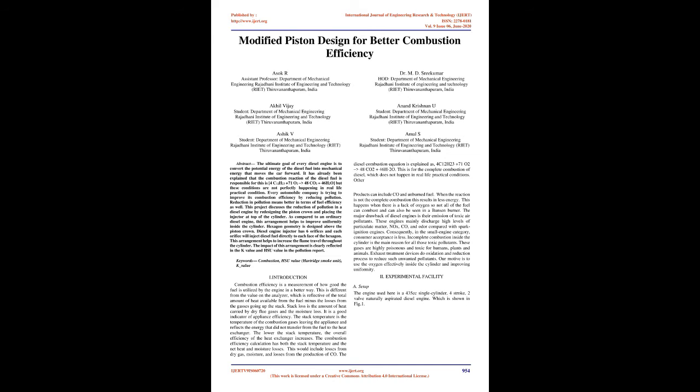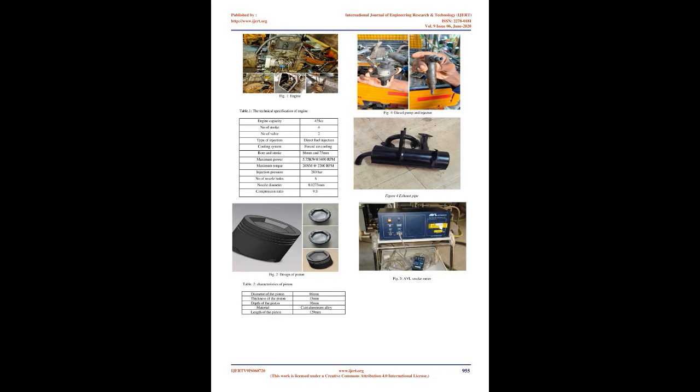The stack temperature is the temperature of the combustion gases leaving the appliance and reflects the energy that did not transfer from the fuel to the heat exchanger. The lower the stack temperature, the higher the overall efficiency of the heat exchanger. The combustion efficiency calculation has both the stack temperature and the net heat and moisture losses. This would include losses from dry gas, moisture, and losses from the production of CO.